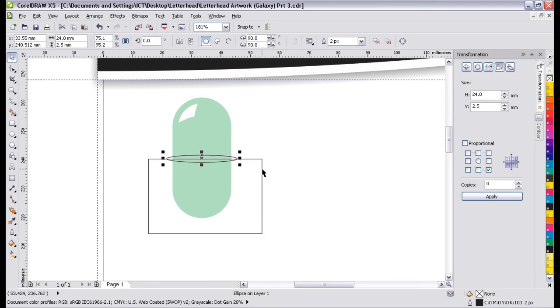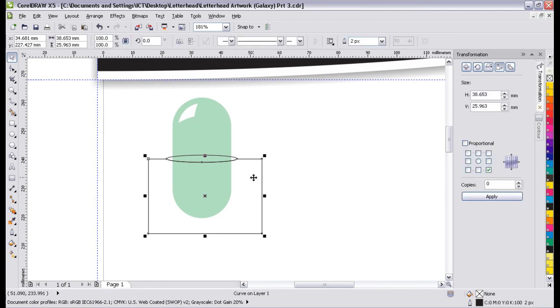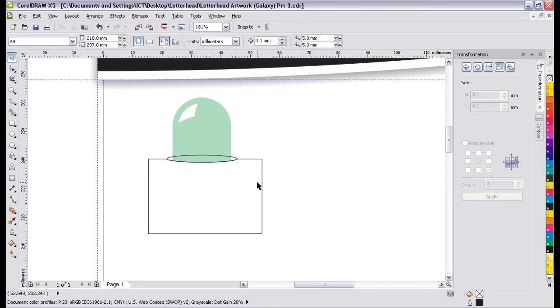So select the ellipse, Shift, select, trim. I've now got an object or a cutter that I can use to chop this glass. Okay, so I'm going to select the rectangle, hit Shift, select the glass, and then trim. There we go. Then I can delete my little cutter.